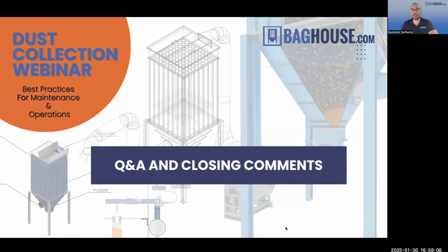And I really like that now we have devices that we sell that are the automatic DP line cleaners. And my goodness, dude, those save money if you put them in, because then every few minutes they shoot air back in to blow the line out. And it saves so much headache. Otherwise people would either do that or just make it part of the PM to check those gauges and get them reading. Because sometimes we go out, right?